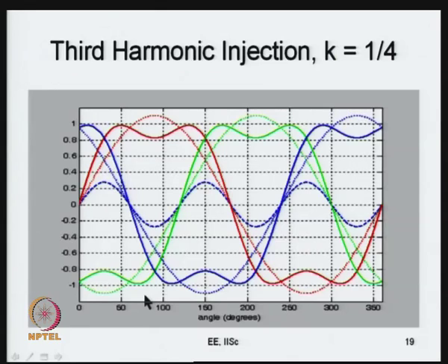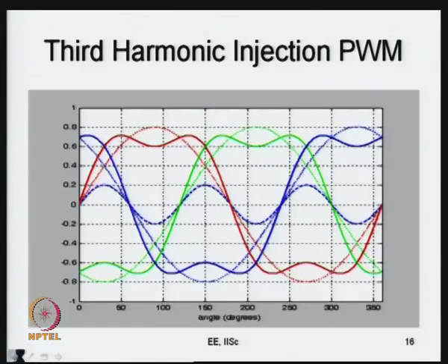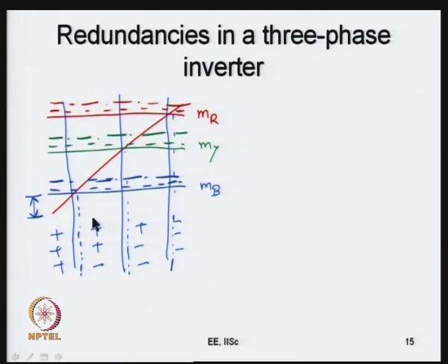What it really does internally is divide these two zero state times equally, plus plus plus and minus minus minus; it makes them more or less equal, that is what it does.